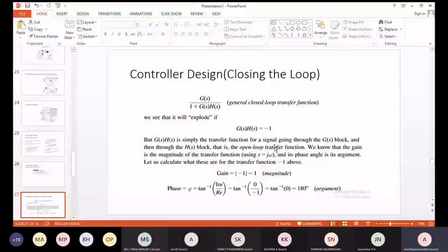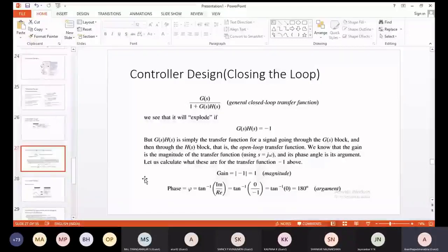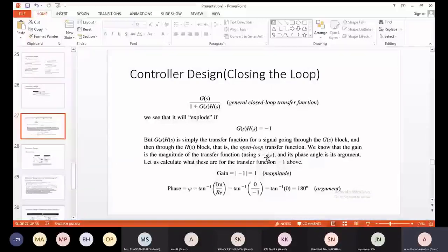So the danger point is that the gain is equal to 1 and the phase becomes 180 degrees. We should be sufficiently away from the danger point, and that distance is called the phase margin. So the phase margin is very much essential to keep away from the danger point of the magnitude becoming 1. All control system design, in a nutshell, is how to stay away from this, while keeping all the other parameters like overshoot, undershoot and steady state accuracy.